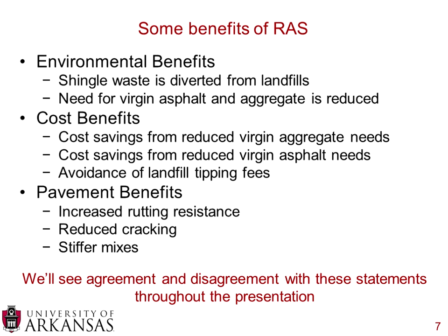These are some of the benefits of RAS. There are environmental benefits. You can divert shingle waste from landfills, and your need for virgin asphalt and virgin aggregate, that mineral filler and the small mineral aggregate, is reduced. You have some cost benefits because you're not only reducing your virgin material needs, but then either the manufacturer of the shingles or the people disposing of tear-off shingles don't need to pay landfill fees as well. So it's kind of a win-win situation. Someone's trying to get rid of something that they usually pay to get rid of. Someone's trying to get something they usually pay to get. So there'll be some savings on both sides of that.